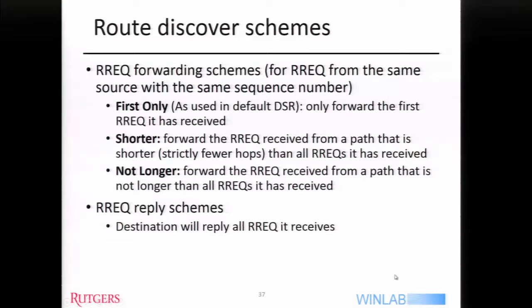If I can assume somehow synchronization, then I can just sequentially measure all 64 and maybe find out what are the top strongest. According to some minimum performance, maybe I have 3 that are viable, and then I put it in memory. So this could be, like in your case, 3 routes that are viable, which happens to be 3 combinations of angles. Yeah. We can have a code book. There are also pattern matrices, and other structures that are likely to be very efficient as implemented as a discrete set of directions, as opposed to fully controllable phase shifters and magnitude controllers.